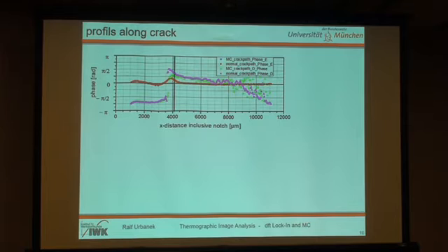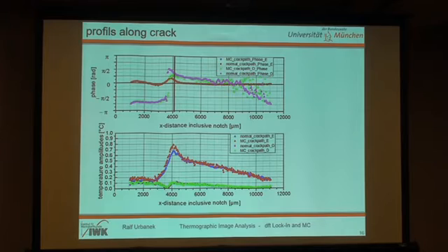So have a look at our result from the potential drop, but the potential drop says there is a crack tip. And if we compare this with our E amplitude, we see the shifting effect that is compensated via motion compensation, and we see that the crack tip matches with the hottest, or the place where the highest amplitude of